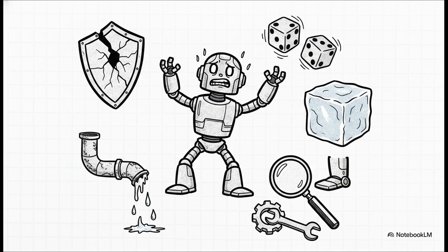First, if you randomize your simulator too much, like if you tell it the floor might be made of pure ice or superglue, the robot gets so terrified it won't even take an optimal step. But too little randomization, and it can't handle the real world at all. You gotta match the expected real-world vibe. Third, misidentified parameter spaces. If you waste time randomizing the camera color when the actual physical problem is a motor delay, your robot is still gonna fail.